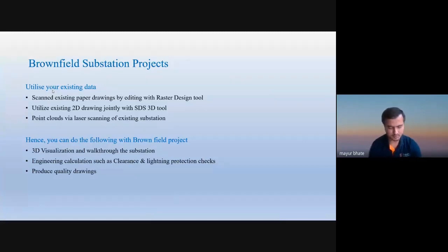And this software, Substation Design Suite, is also very useful in such brownfield projects. A substation designer can utilize the existing data by scanning the existing drawings and editing them with the Raster Design tool. It is a tool that is basically available in Autodesk software that you can research some other time. Then we can utilize the existing 2D drawings and convert them into a 3D layout using the 3D design tool made available by Substation Design Suite.